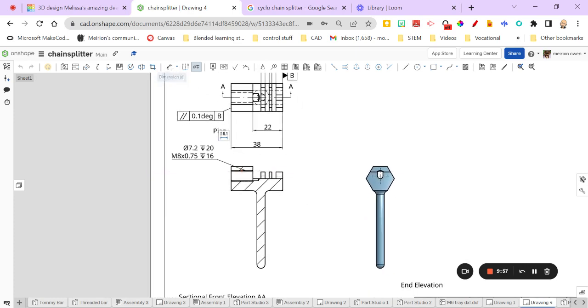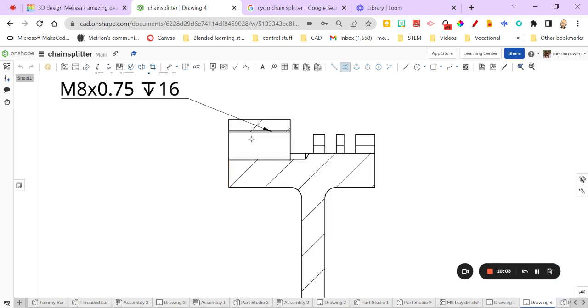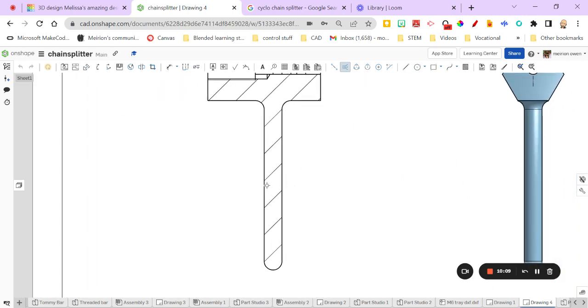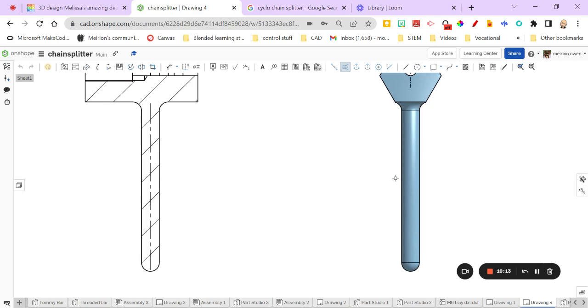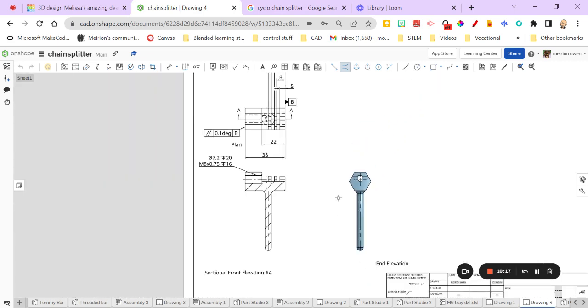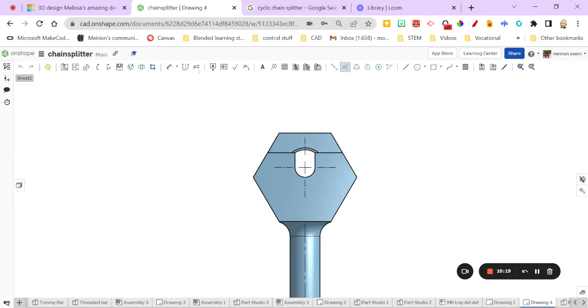Let's put some center lines in. That's often a good thing to do. So center lines can be put in a number of ways. Quite like this edge to edge center line that you can use. We click on two edges and it'll drop a center line into something. Putting center lines over hatching lines, that's not something we tend to do, but you can if you want to. Same on that one. So we've got some center lines and we can start dimensioning bits.